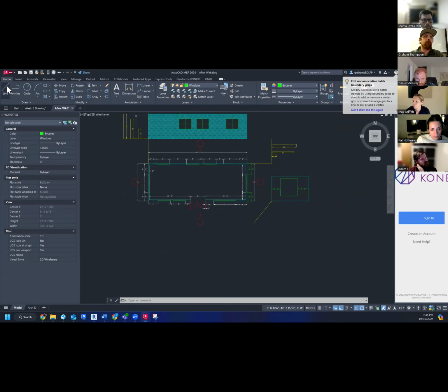So here, let's copy it down. Good idea. I'll put a construction line on here, give us our 10-foot space distance. Again, I like 10 feet just to give you some working room. If you make it too close, you're on top of yourself. Okay, I'm just going to make that 40 feet over. All right, so this is where it gets a little tricky, but let's just go. I'm just going to quickly go through this again. Sorry, this should just be 10.